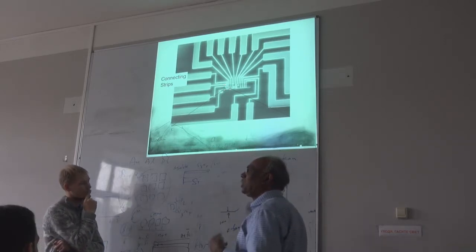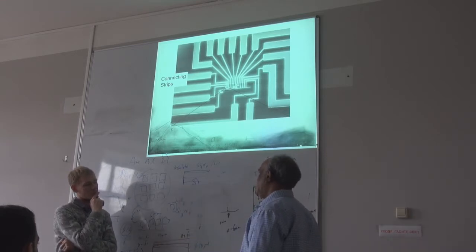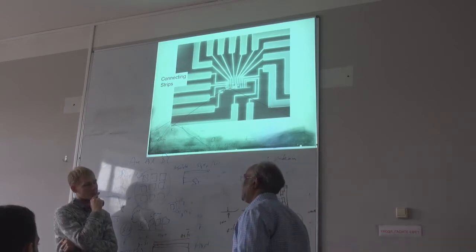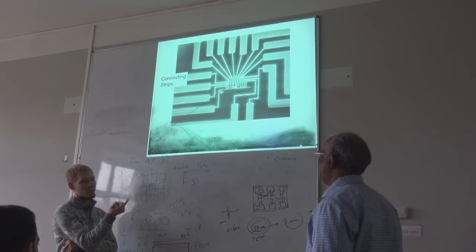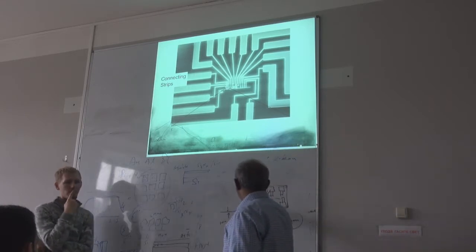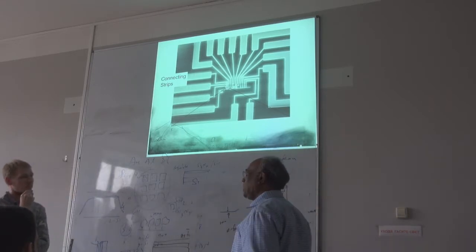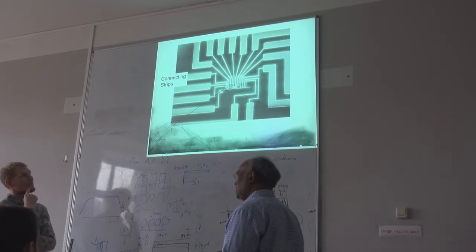Then you do the same thing, you just develop and etch, and you can make contact to this one. You write little electrodes and can measure the properties. But in one chip like that, we make about 5 devices. I can make 5 carbon nanotube devices.